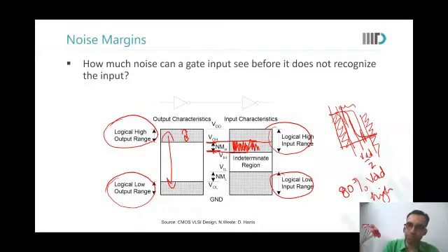Okay, sir. So if the output of one gate is fed into another, the noise gets overlapped with the output. So let us look at it like this. I made a very good output curve over here. I followed this. Okay. Now in between, I had some coupling capacitance coming into the picture with another wire, and therefore by the time it reached here, my output fell a little. I was giving an output high of this.